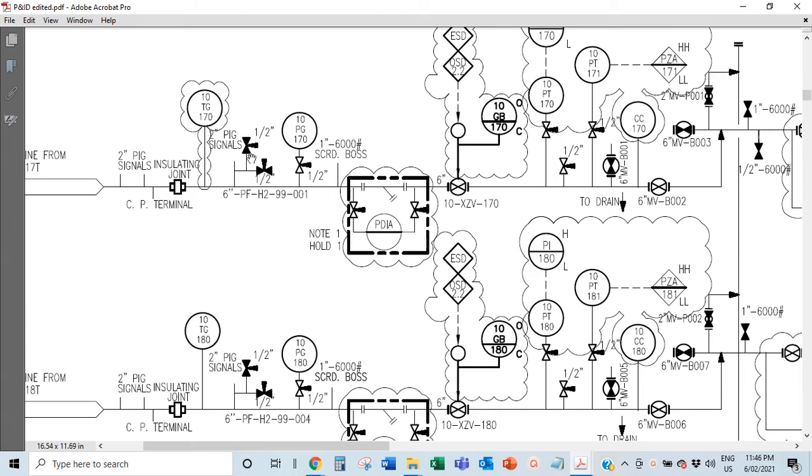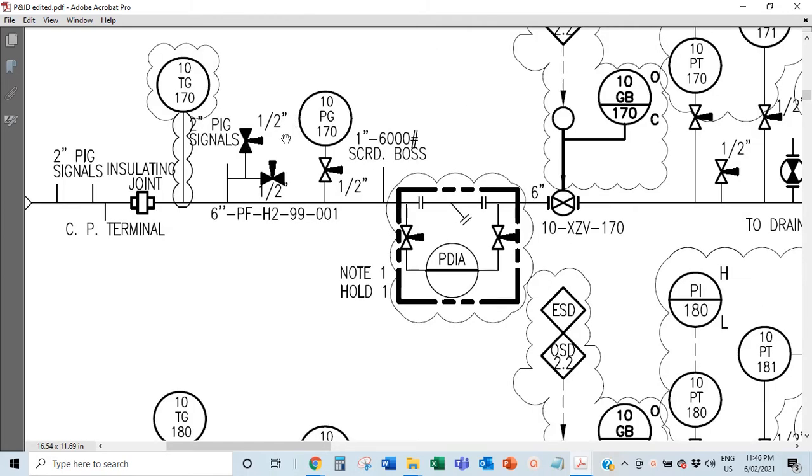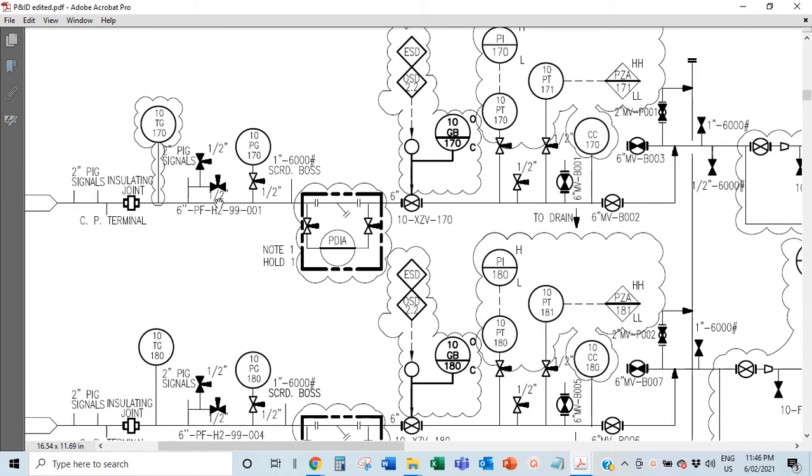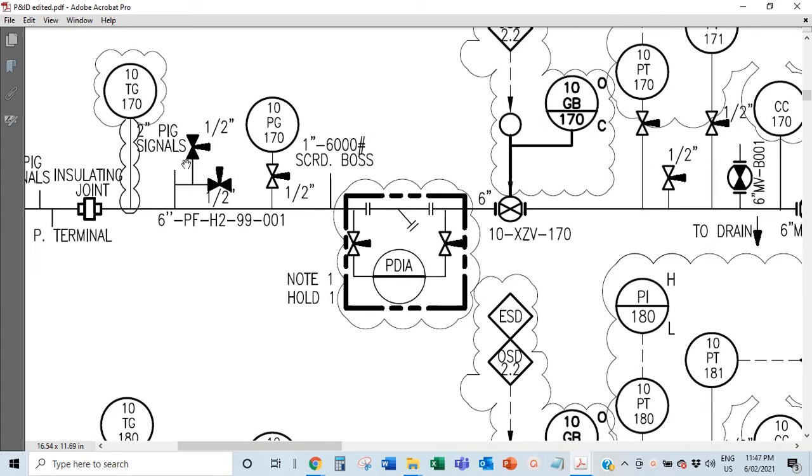So then going upwards, these are needle valves. If you go and look at the legend, you would see that these are needle valves, and needle valves are mainly used for throttling, like finely controlling the flow in a very meticulous way, just to make sure that you're getting this exact amount of flow. Because some of them are blacked off, that means they are closed. They are not exactly locked closed, but they are not open.